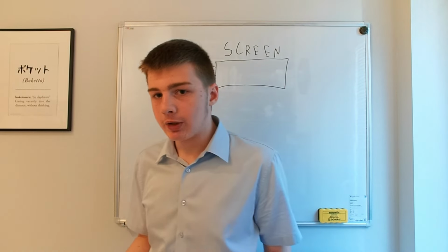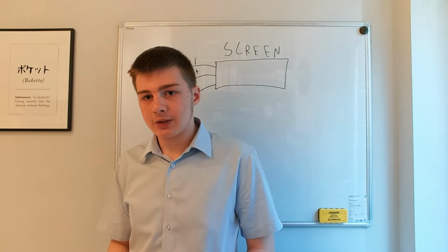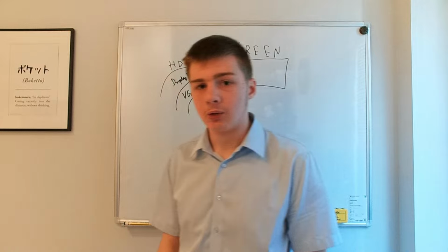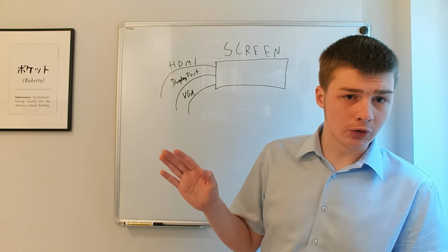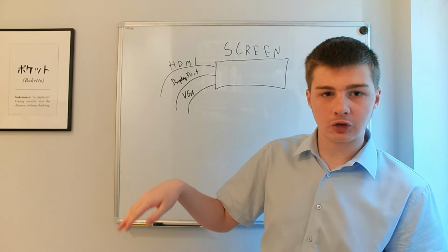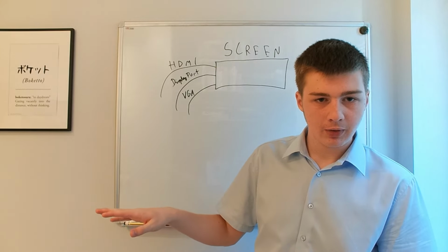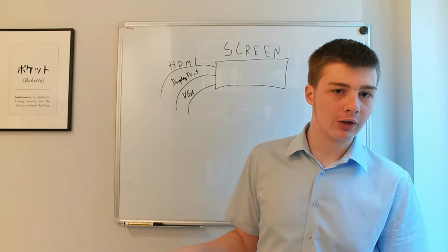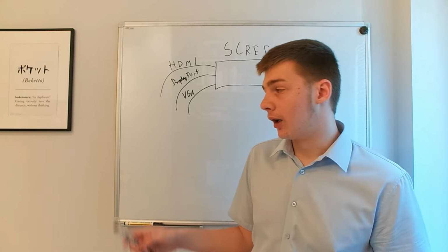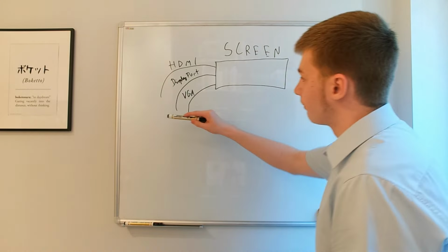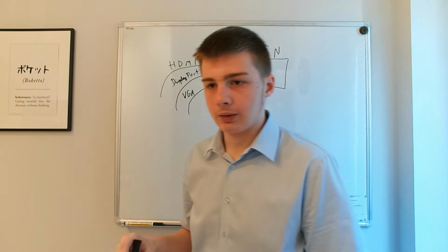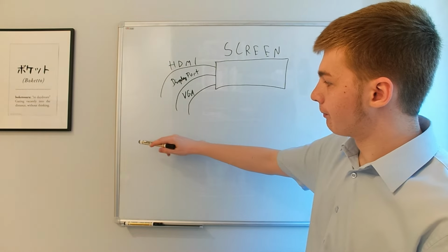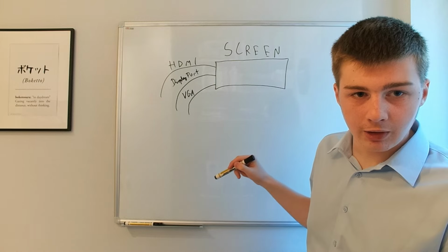Fundamentally, a mode, a VGA mode, is pretty much described in timing, right? It would be synchronous in the sense that those electrical signals would have to be sent in specific timings according to a given graphical clock or video clock, which would dictate the signals.